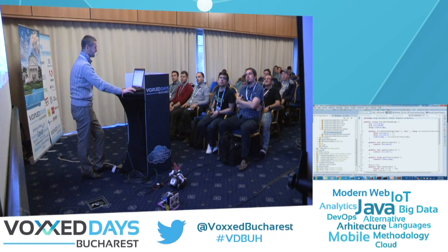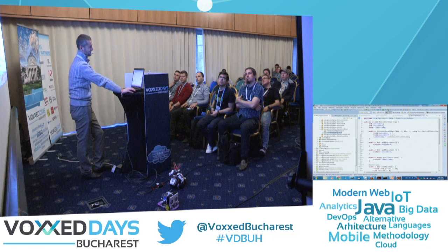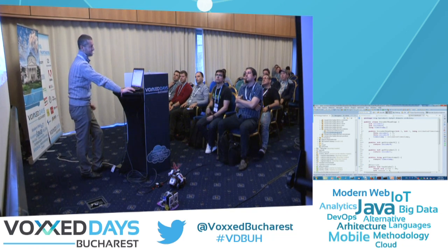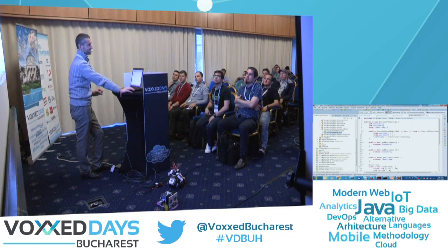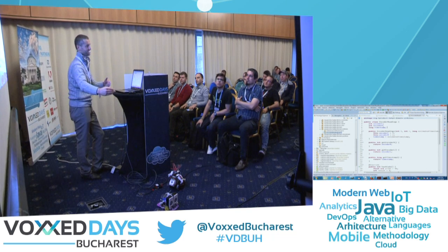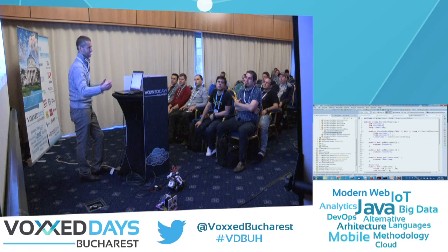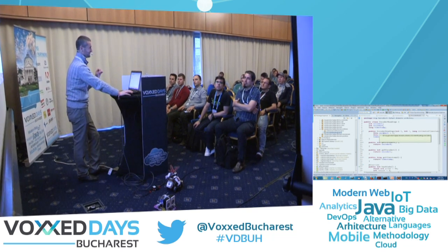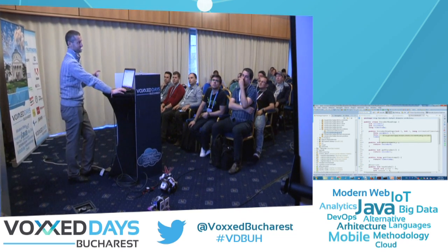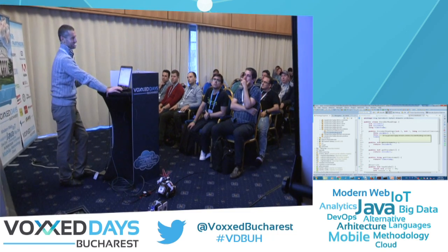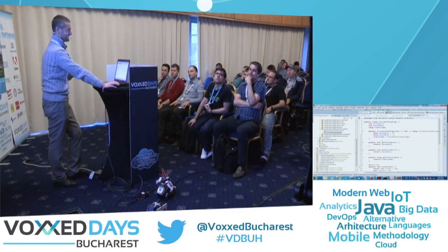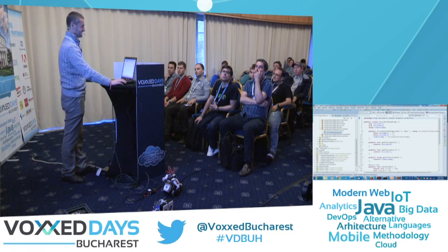So we have actually two values, left encoder, right encoder, and very important, the timestamp. Without it, you don't know the latency of the communication. It's serial communication, it's not real-time communication. And for acceleration, it's very important to know the difference in order to compute exactly the formulas. They're time-based derivatives. So that's why I need the timestamp.